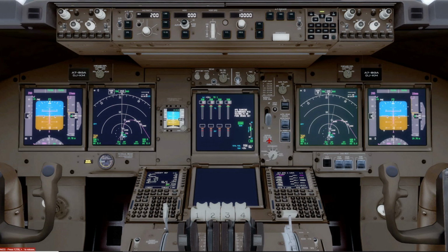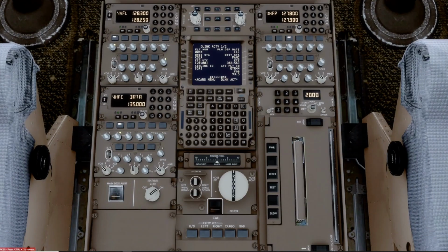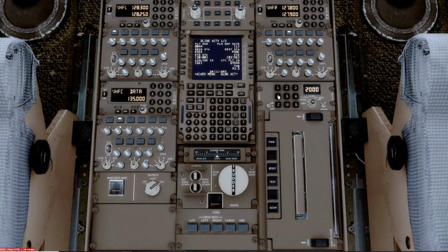So we got the ATIS, and then we pick up our clearance, and we'll say we've got our clearance, and let's say we're cleared to 2000 on departure, and we're cleared via the Bangor 9 departure. Flight plan route to maintain 2000. Expect flight level 340 10 minutes after departure. Departure will be 119.2, and they say squawk 4223. So we'll come down and squawk 4223. We've got our clearance, 4223.